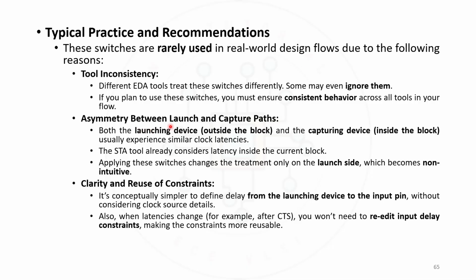Next, asymmetric behavior between the launch and the capture paths. Both the launching device, which is outside the block, and the capturing device inside our block usually experience similar clock latency. The STA tool already considers latency inside the current block. Applying these switches changes the treatment only on the launch side, which becomes non-intuitive. Coming to the clarity and reuse of the constraints, it's conceptually simpler to define delay from the launching device to the input pin without considering clock source details. Also, when latency changes, you won't need to re-edit input delay constraints, making the constraints more reusable.